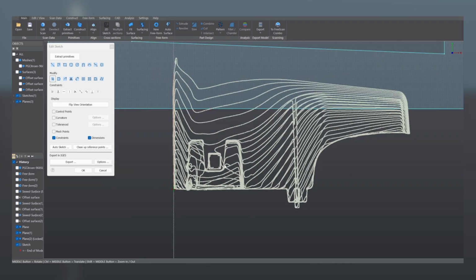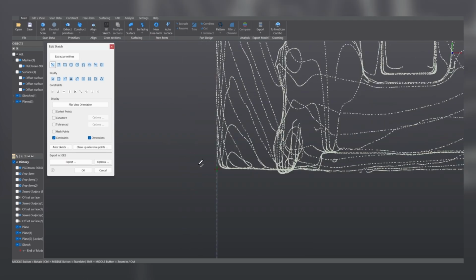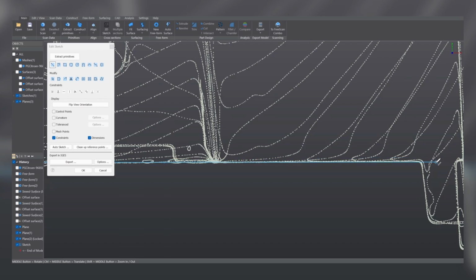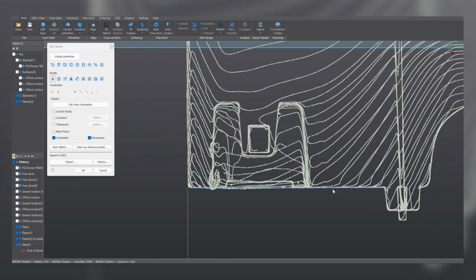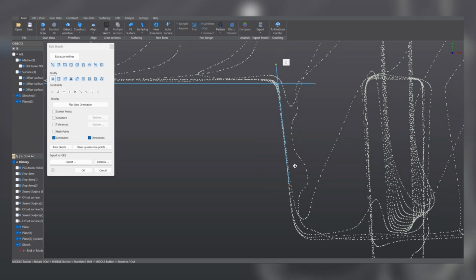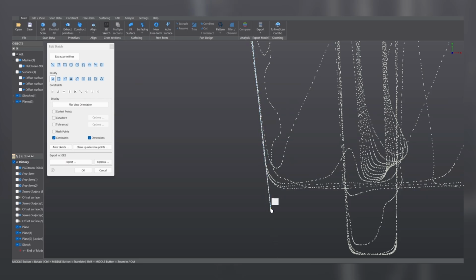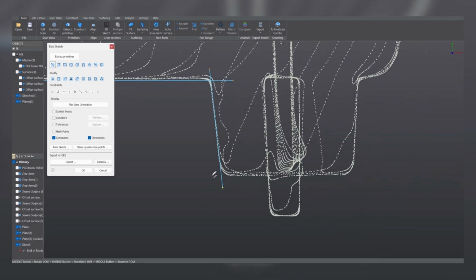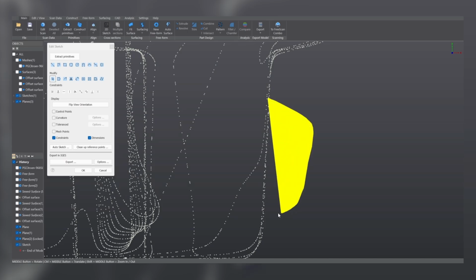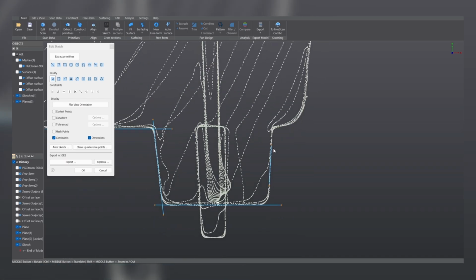And therefore you can clearly see the result that you were looking for. Now, what we do is let's start here in the origin. Let's draw a horizontal line like this. Actually, let's click on it and make sure that it's horizontal. And now let's reproduce this geometry. How? Well, with the Shift key and selecting the points, you can quickly best fit lines. Here, actually, I will eyeball one horizontal line on the top of this shape. Here, let's also best fit a line, like so.